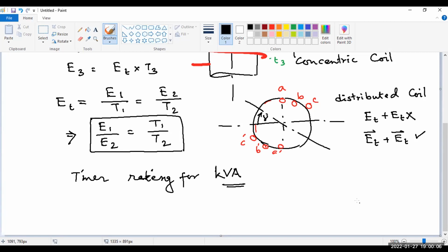Okay, so that means if we don't have any current in the secondary side, but still we'll have some current in the primary side. What is that current? The no load current, magnetizing. Okay, so that is the no load current, I0. And that is the vector summation of the magnetizing current and a loss component of current.